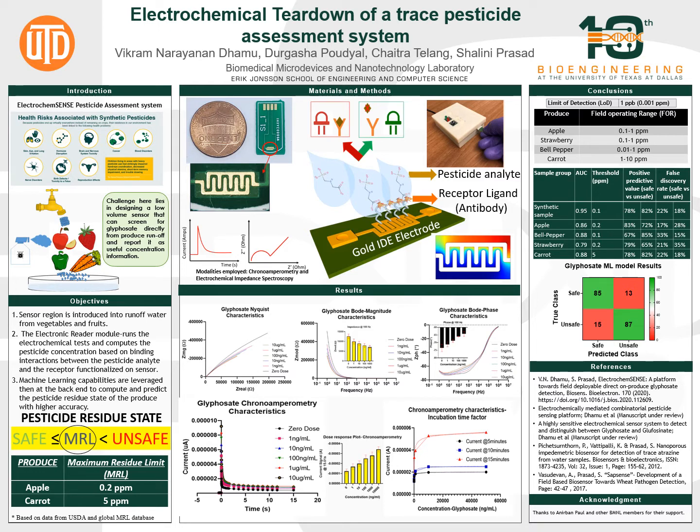Moving into the results, we see the electrochemical impedance spectroscopy results, which are in the form of a Nyquist or a Bode plot. First, we can talk about the Nyquist, where we have the real versus the imaginary portion of impedance, and the bending of the signal with respect to dose shows that the binding effect is being tabulated in terms of the impedance. Next, we move on to the Bode plot, which is measured as a function of the magnitude impedance and the phase impedance, where with more binding, which is modulating the impedance, there's a signal change, and that is shown as a recovered concentration trend here in the form of the bar plot trends in both the magnitude and the phase curves.